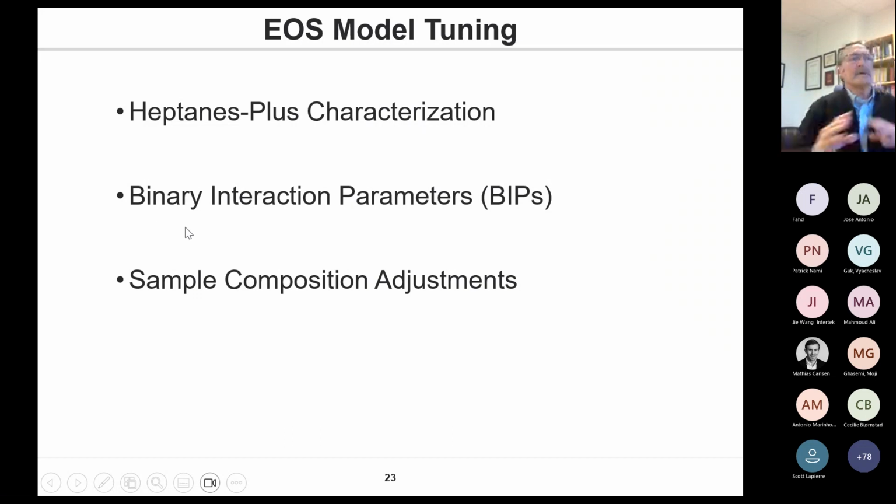And then we've got these binary interaction parameters, which will help us to correct the simplicity of the cubic equation of state in describing very complex interactions amongst binaries and other components, and try to better bring in line the model with measured K values, which give you the actual signature of that particular mixture, the K values, their approach to the dew point or bubble point, and so forth. So the binary interaction parameters are particularly important for modifying how the K values vary with pressure and temperature. So those are the things we can change, and often we'll change preferably as little as possible to get a match to measured vapor, liquid, and volumetric properties of the mixtures of interest.